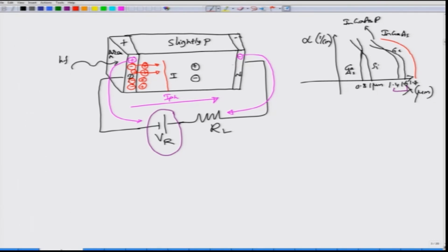The same thing will happen on this side as well. So, there would be these positive charges, right, which are left behind after all the electrons have moved out. In order to balance them out, you will need negative charges, and it so happens that if you choose the doping profiles in a way that normally is chosen, you will actually end up having a net number of charges in the I region to be much larger than the plus regions.